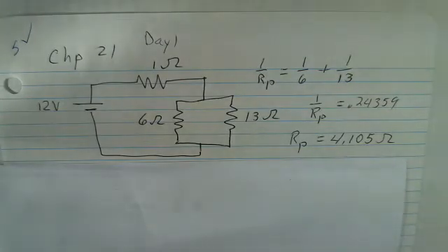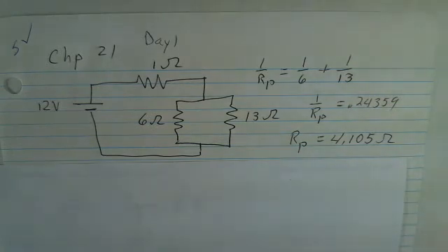Professor Clements with you as we again consider electric circuits, this time with battery and resistors. Our challenge here would be to find the power in each resistor. How would we calculate power? The basic concept: power equals current times the potential difference across the device. So we're going to need to find the current in each resistor.